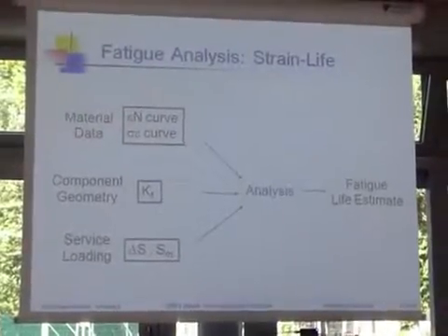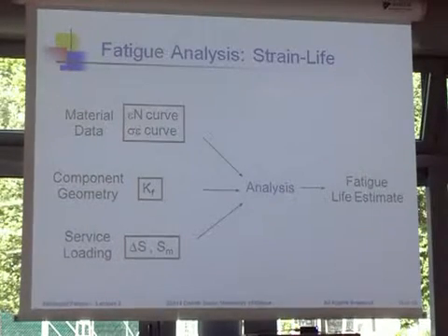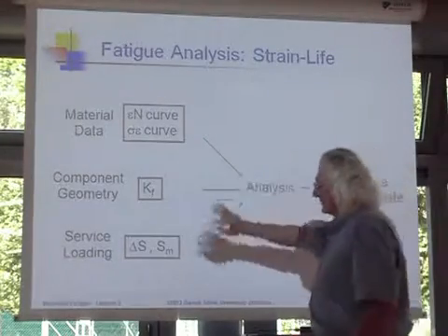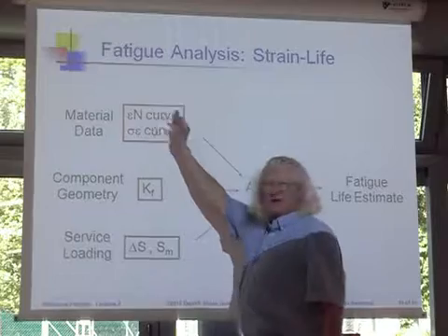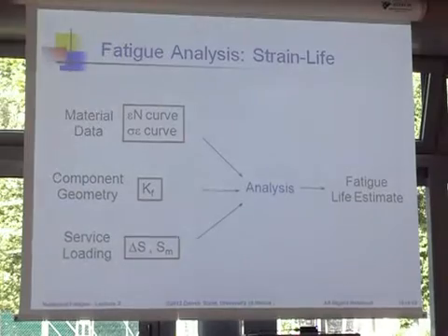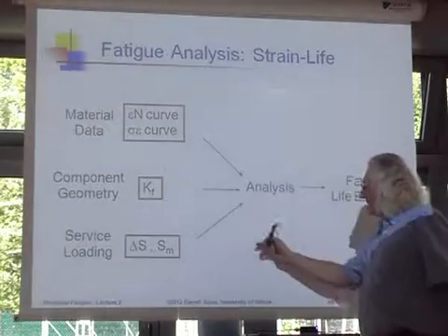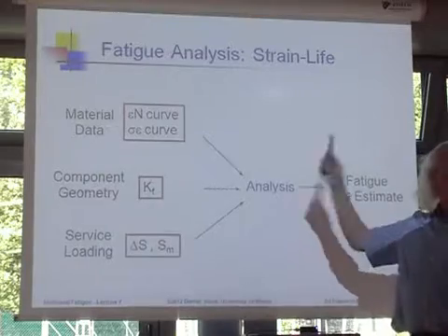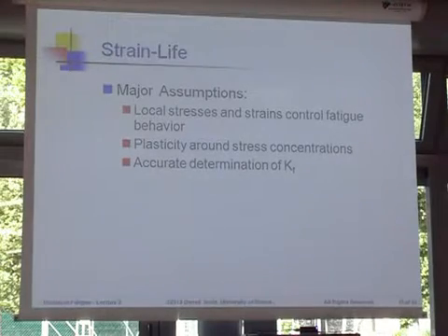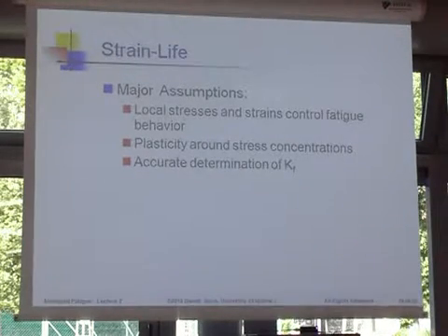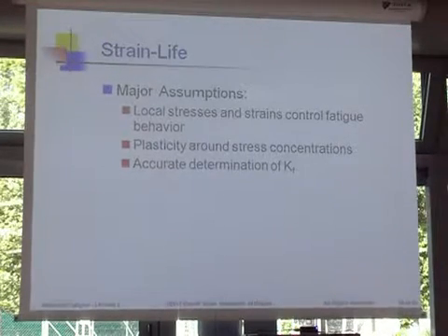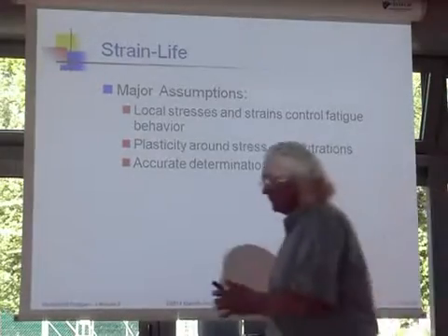Right. So I have the same analysis template. The real part of doing fatigue is really understanding what to do. Same loading, same geometry. The only difference is I need a little bit different material property now that gets all of this plasticity. But the inputs are the same, and of course this part doesn't. This I'm not going to do longhand either. This I'm going to shove in some computer, so it's just as easy to do one of them versus another. And so the assumptions behind this are that it's really these local stresses and strains, and what's important is the plasticity around the stress concentrators drives the process, just like this, right?